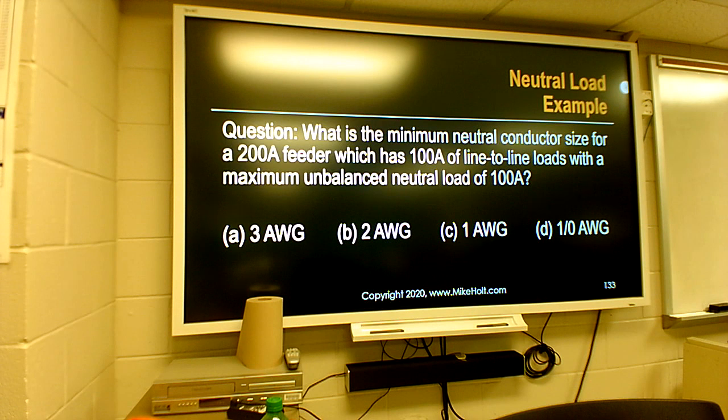So your heating elements that's in your cooktops and anything like that, the ovens and all, they don't use a neutral. They use two highs. So the current is actually flowing using L1 and L2 for 240 volt, and there's no neutral current flowing for the heater elements. The only neutral current you would have in that appliance would be running the electronics, possibly, like the display or something like that. You know what I mean? But if a neutral is used in there, it would be used on the things that are not the heater element.